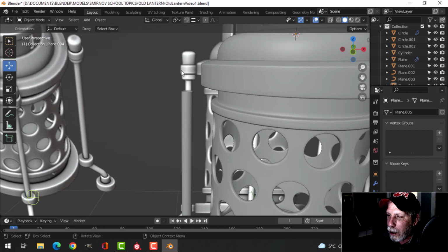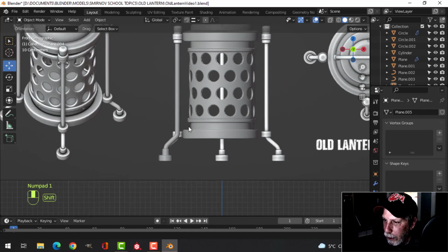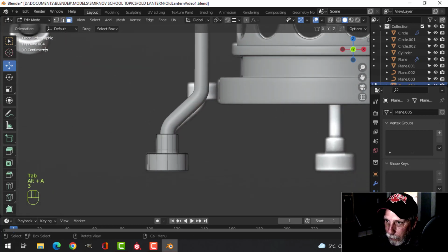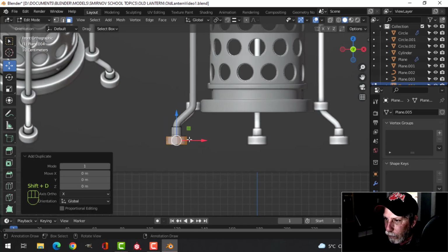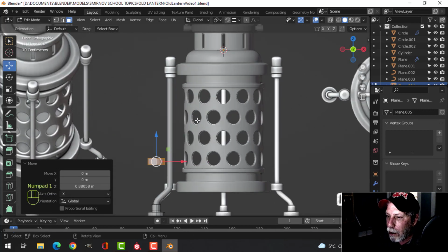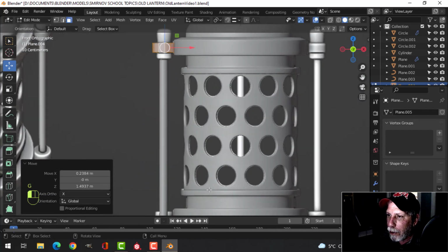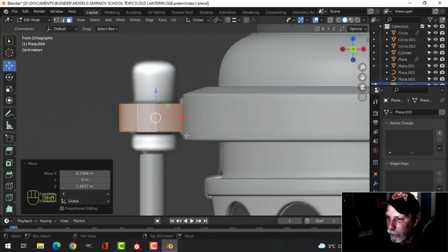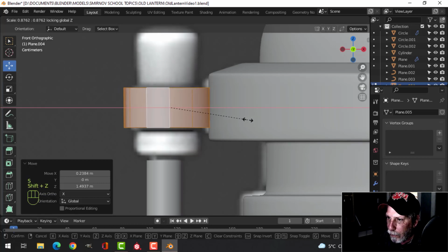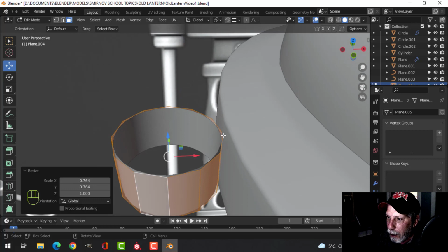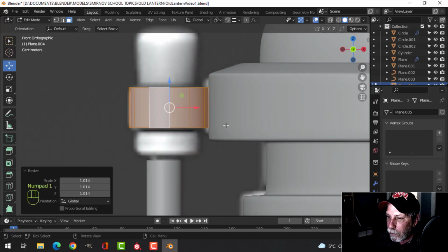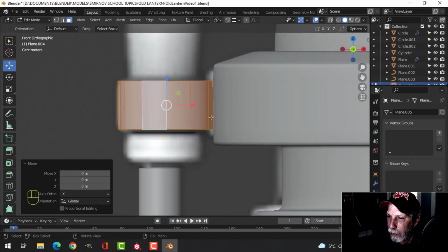And now let's create this part here. You know, I like to just reuse circles. I'm going to do this in mesh, so I'm going to take this. And in fact, in face selection, Shift Alt and click there, Shift D and pull it up so I get all of that with the subdivision already on it. I think I may use that. So I'm going to press G and I'm going to come up here. All right. And I'm going to make it a little bit smaller, but not in the Z. So I'm going to scale Shift Z and just sort of pull it in. And the idea is that this would just sort of weld onto that. So I'm just going to press S, just touch it there. Okay, so that's pretty good.